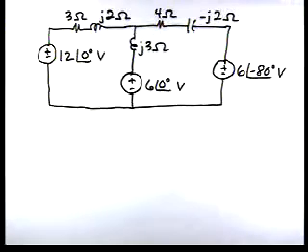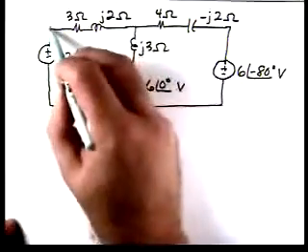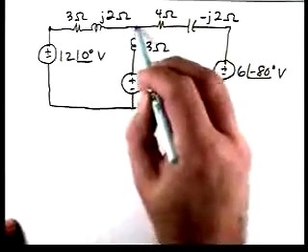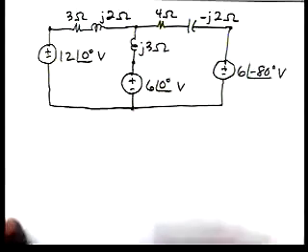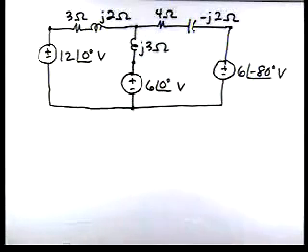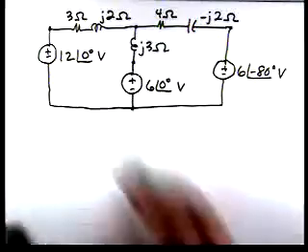And if we look at this and think about how we want to analyze it, we're going to need the voltage across or the current through the resistors. Let's look at the number of nodes. For instance, here's a node. This is 2, 3, 4. There are 5 nodes. Now, if we look, though, 3 of the node voltages are known.